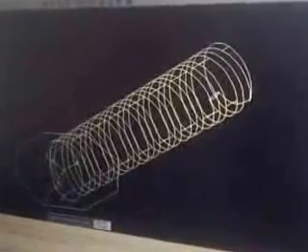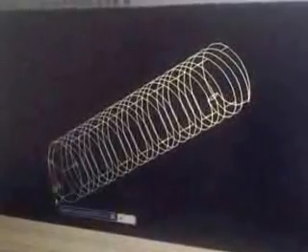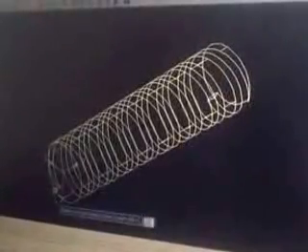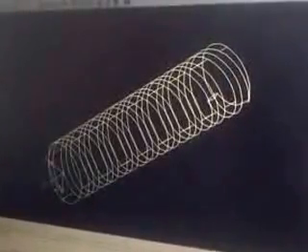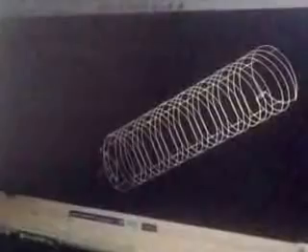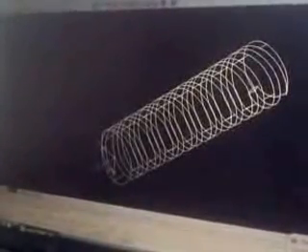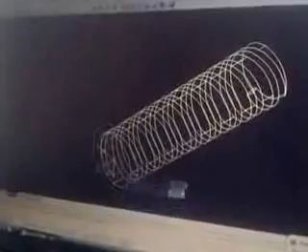Now you can see the position is not like that, so you have to make your z-axis in the right position. So you go back, polygon, number of sides, yes. We need it at a position of 0, 0, 0, inscribed in a circle. Yep, then you have it.